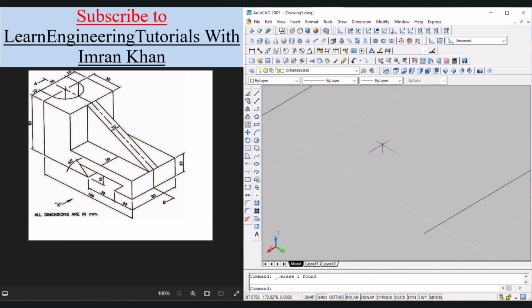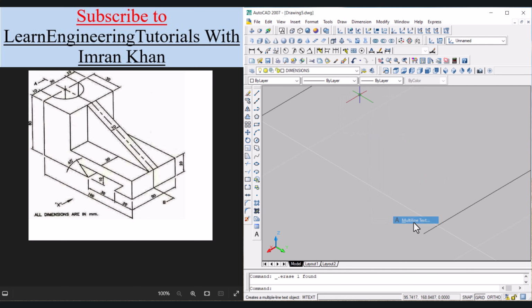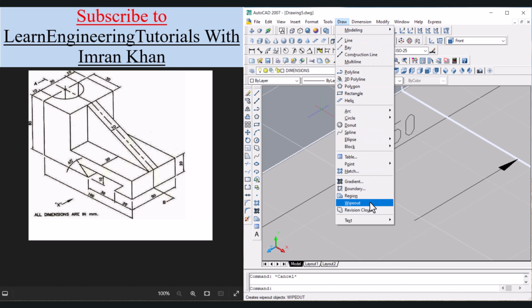Now we have to add a text here. So click on draw, click on text, click on multi-line text. Before that, we have to select the view in which we want to draw the object. So click on front view, because this is the front direction. Now you have to go to draw, text, multi-line text.